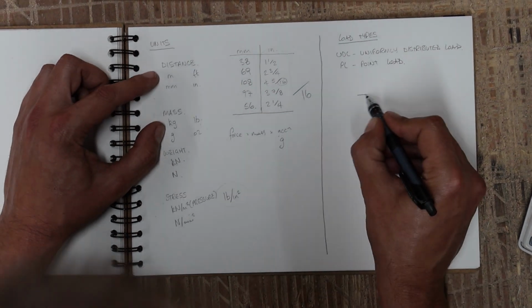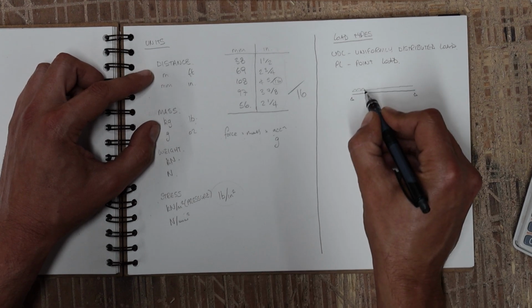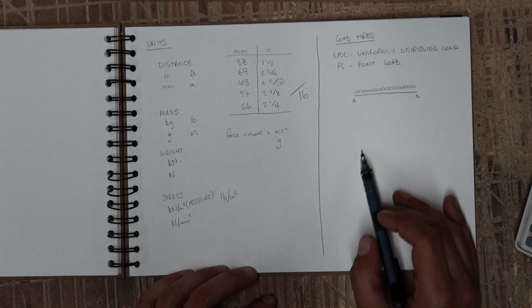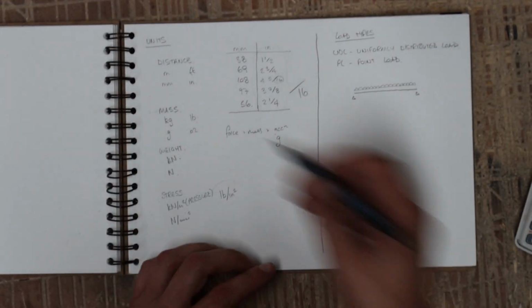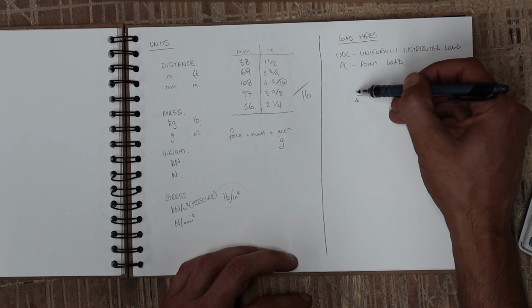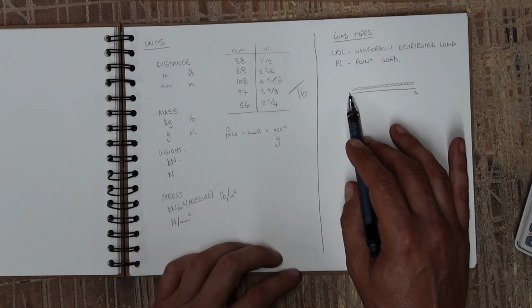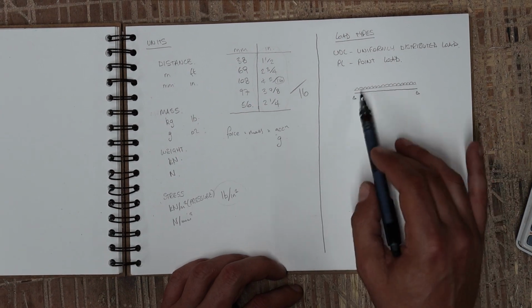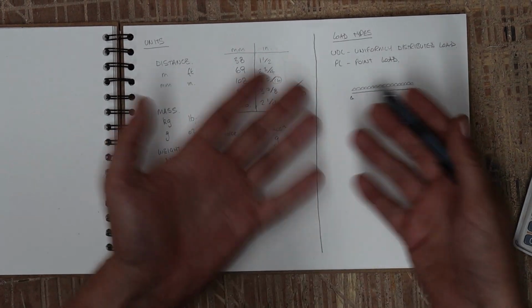And if we had a beam, the way we would draw that on that beam is as follows. We would have a squiggly line like so. The best way to imagine this is that on this beam, you put, I don't know, a foot, or 300 millimeters of sand over its complete length, so that all of the load is evenly distributed over its complete length, i.e. a uniformly distributed load. That's what that would be. This is fairly common, I do this all the time because, with floor joists and beams, we have a uniformly distributed load we need to take for the floor. So this is fairly commonplace.